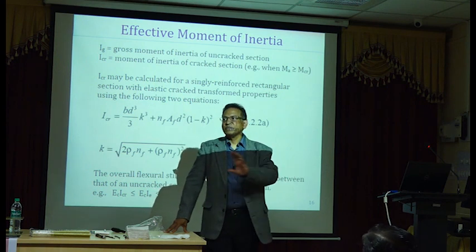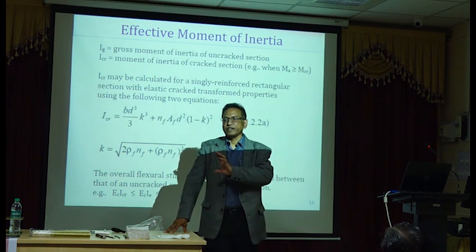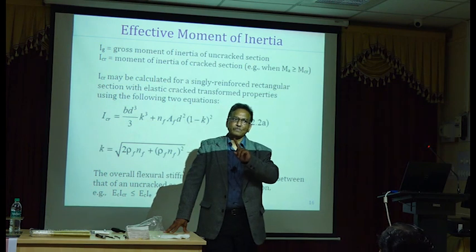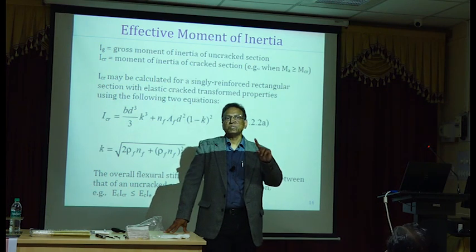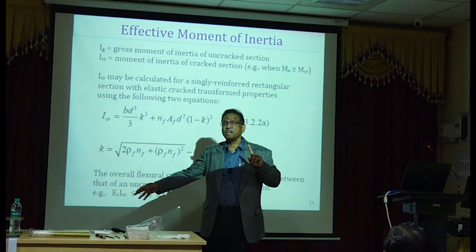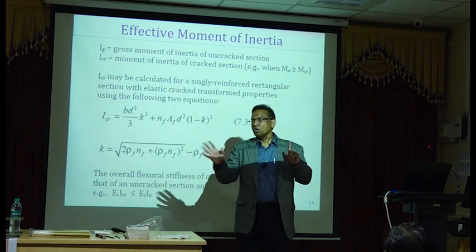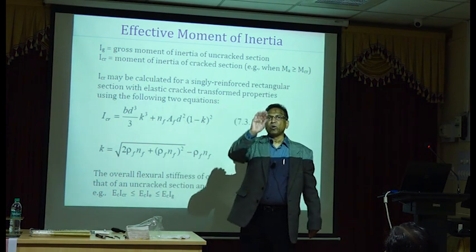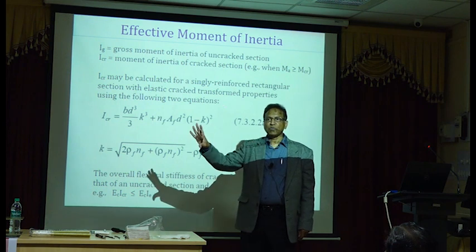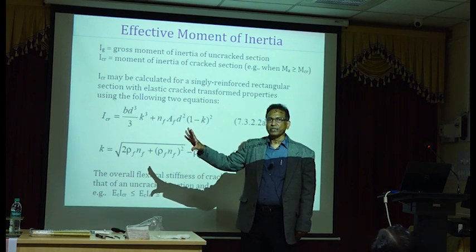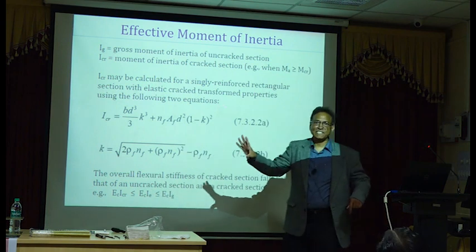Under the serviceability limit state, our factors are different. They are normally 1, right? You remember? Except for wind and other things, you use 0.8. But for dead load and live load, our factors are 1 and 1. Am I right? At least in ACI, that's what it is.